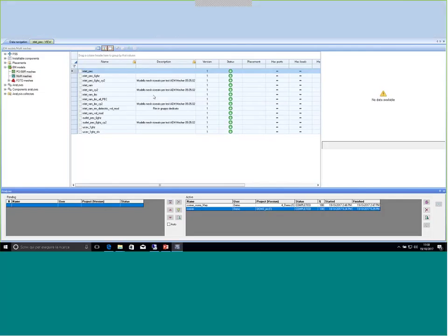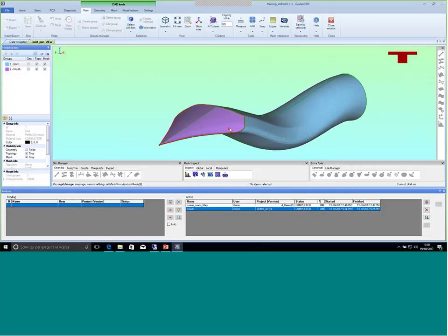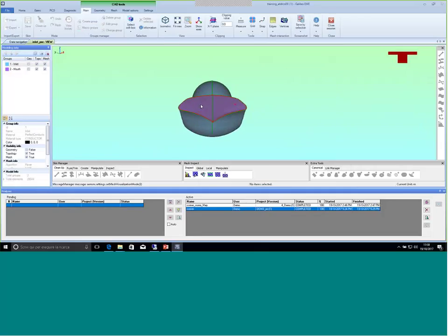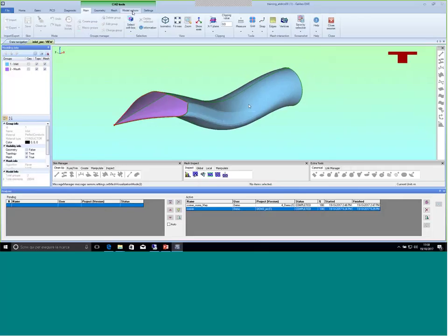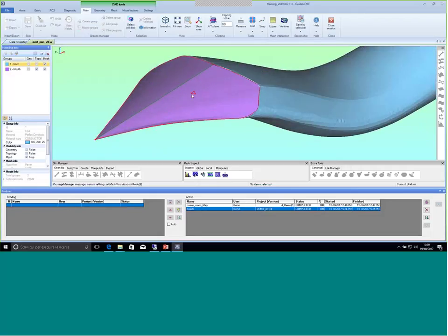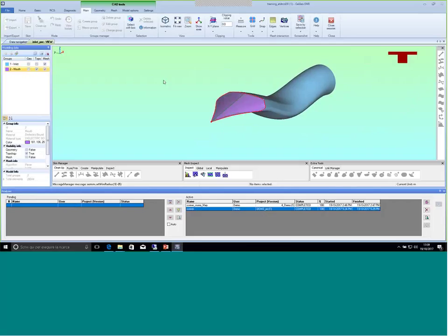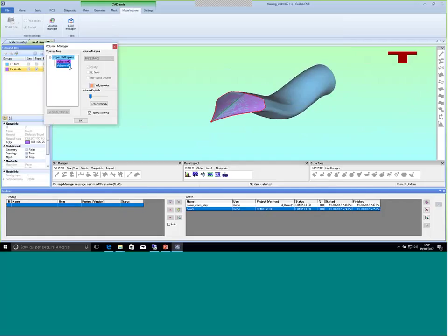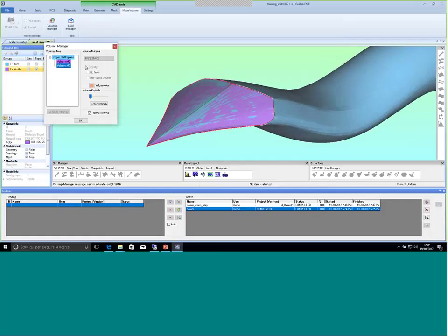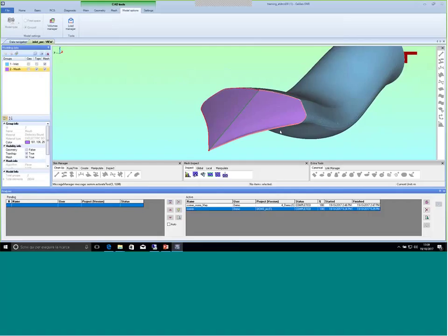Like I mentioned, in this case, it's better if we use the decoupling procedure approach, because when I simulate these targets, I don't want the external contribution of the cavity. So for this reason, I have generated the mesh of the inlet that is here, and also the mesh of this mouth here. Just defining this model and setting here in this internal volume with the flag cavity, the solver will neglect all the external contribution from the cavity and will consider just the backscattered field from this mouth.